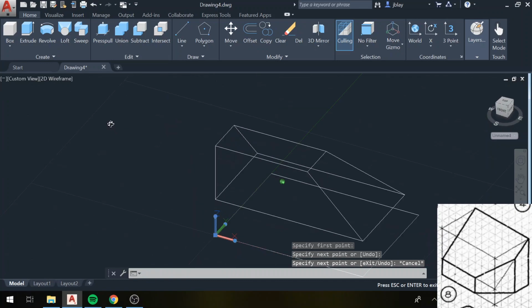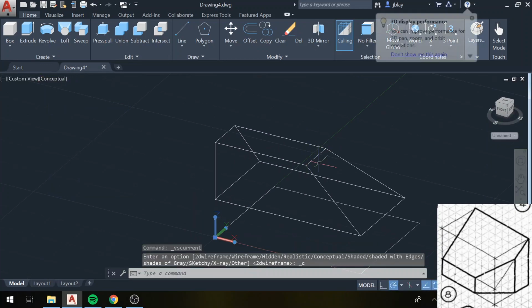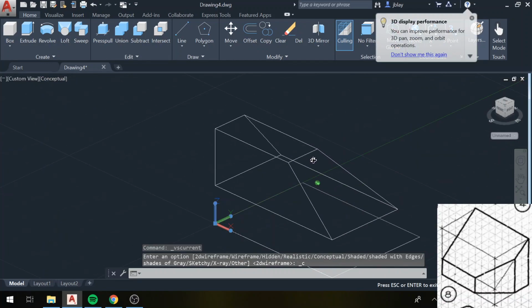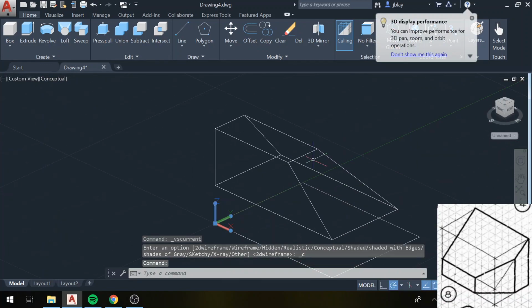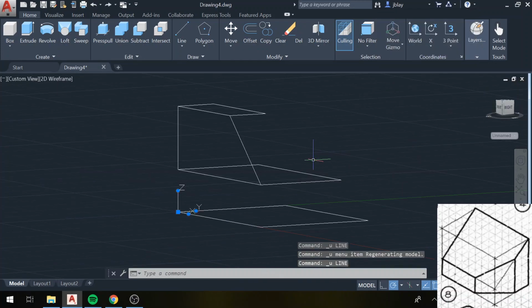If I go into conceptual, you'll see this is not a solid object. If I try to 3D print this, nothing would happen. I actually need to extrude something to get an extrusion, to get a solid object. So what do I do to do that? I need to go to Loft.